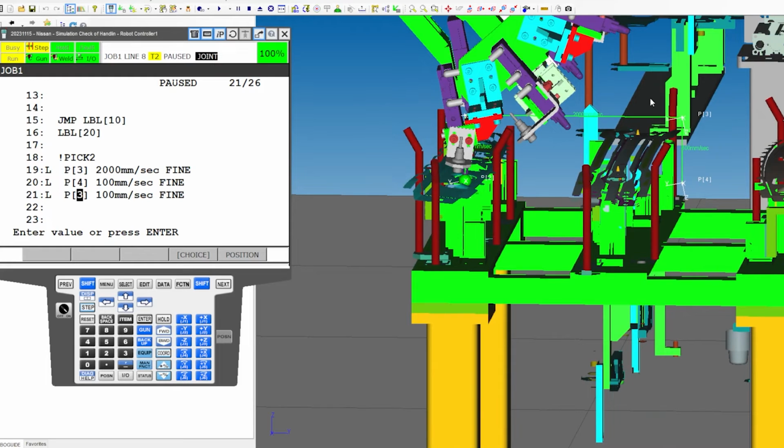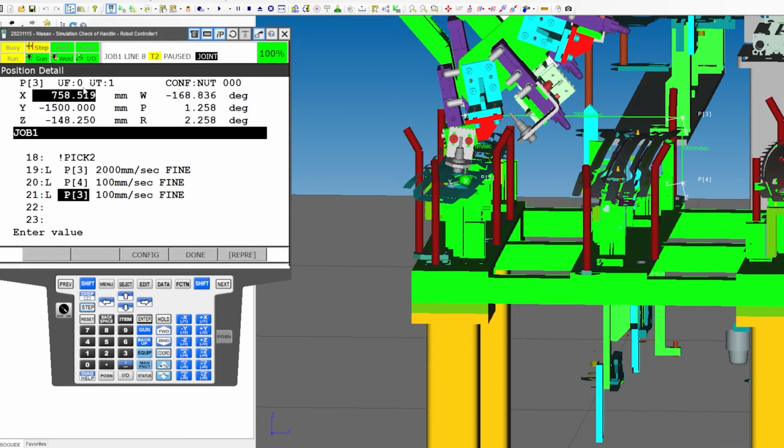Okay? Now, in the real world, let's say for instance I wanted this to be pickup number 2. I can adjust these again. You know, maybe let's just do that real quick. Position, give us some more real world. Let's say negative 1000, just see how it looks. Too far. Go negative 1100. Nice thing about Roboguide is you can just punch in random numbers until you get something that you like, and you can see the data change.